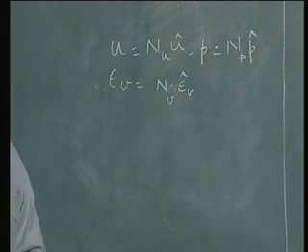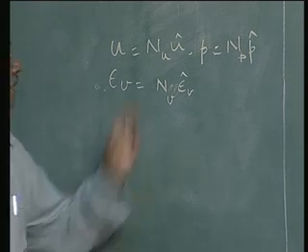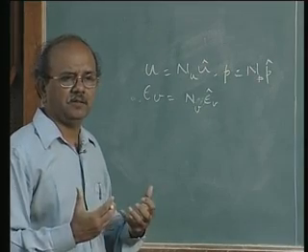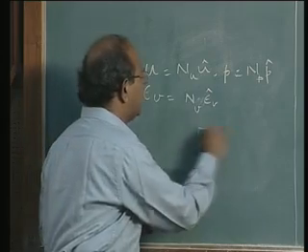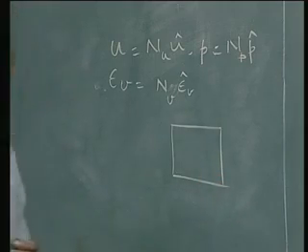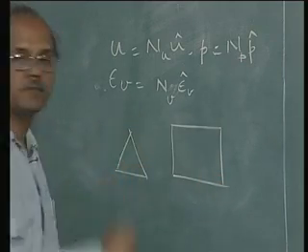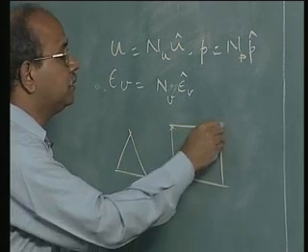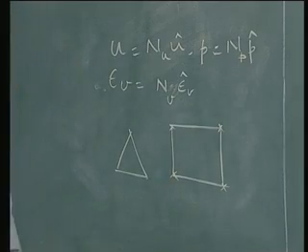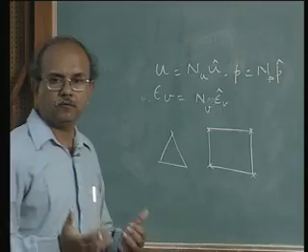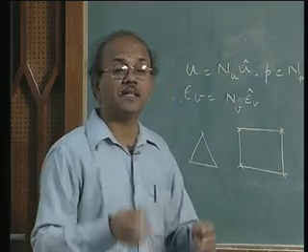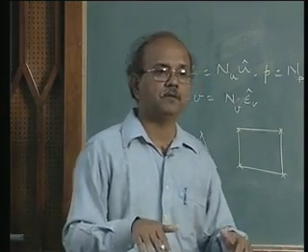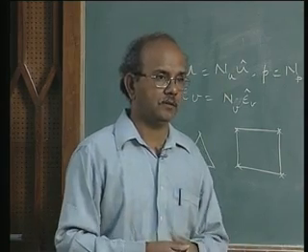It is not necessary that all of them are the same. It simply means that if I have a triangular element, and at the nodes I keep the degrees of freedom for displacement, it is not necessary that at the same node I will keep them for p and for epsilon v as well.